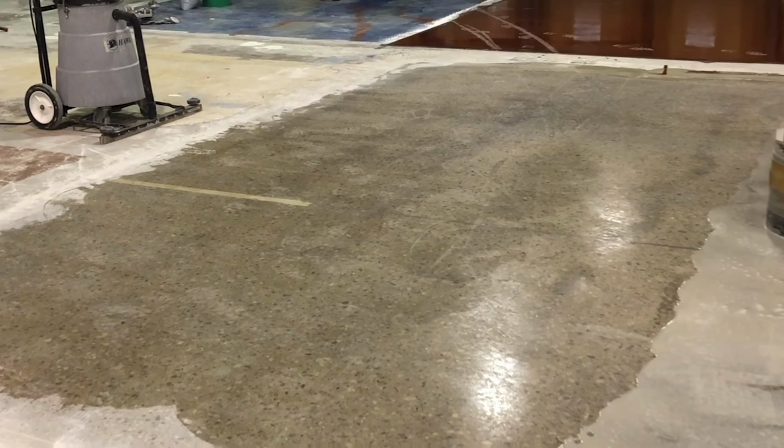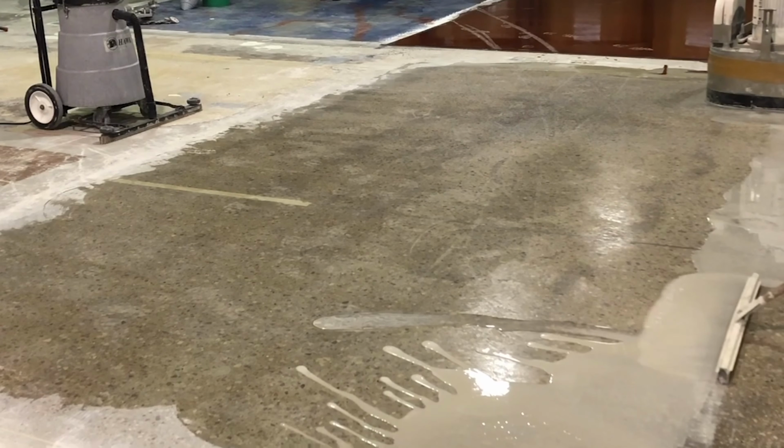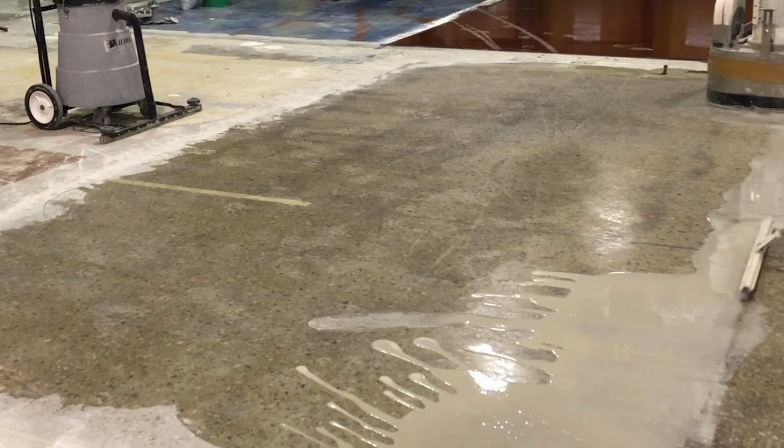Well, speaking from the standpoint of the floor and what it needs, the only reason that I would prefer to do wet grinding or wet polishing would be if the substrate requires it. So concrete polishing at certain points of the process, marble polishing, terrazzo polishing, granite polishing. Those are all processes that require water for the diamonds to do their work with that particular product or floor. So I don't really have a preference of wet or dry.